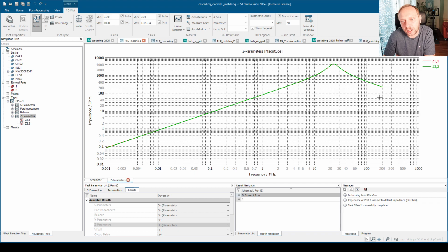Of course, I spent a little bit of time tweaking the values, but it's not really complicated to get these models. If you know the nominal values, you just add this parasitic capacitance, and here you go. You have an RLC model which gives you exactly the same impedance as the Touchstone file. So far, so good. Everything looking great.